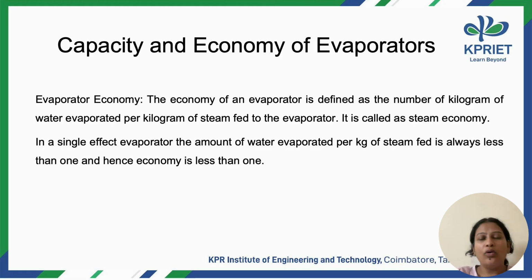This vapor, I do not want to waste it. It is nearly equal to my steam and has all the heat energy, just like my steam. So I do not want to waste that vapor. It will be taken and sent into the next effect, right? Here the water that is converted into vapor also has a very good amount of heat. That heat is used to heat the solution in the second effect. Again, the second effect gives off some vapors, which will be sent to the third effect.